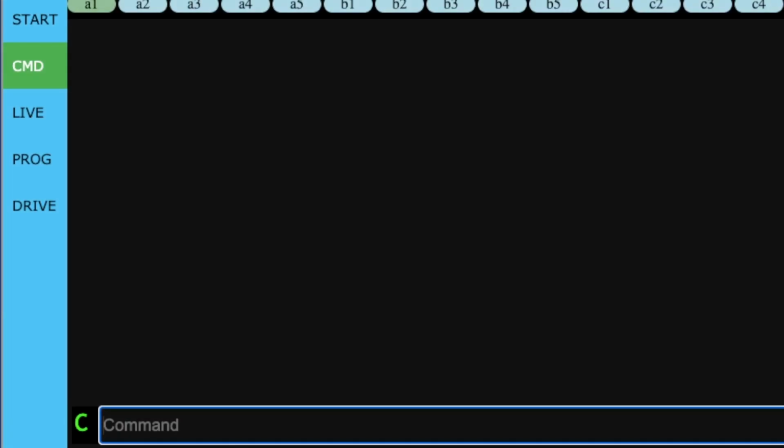Click the CMD button on the top left-hand side of the page to go to the command page. Then at the prompt, type L1 space 1, and the user LED on your JackBord should go white. Then try L1 space 3. This should make the user LED go red.